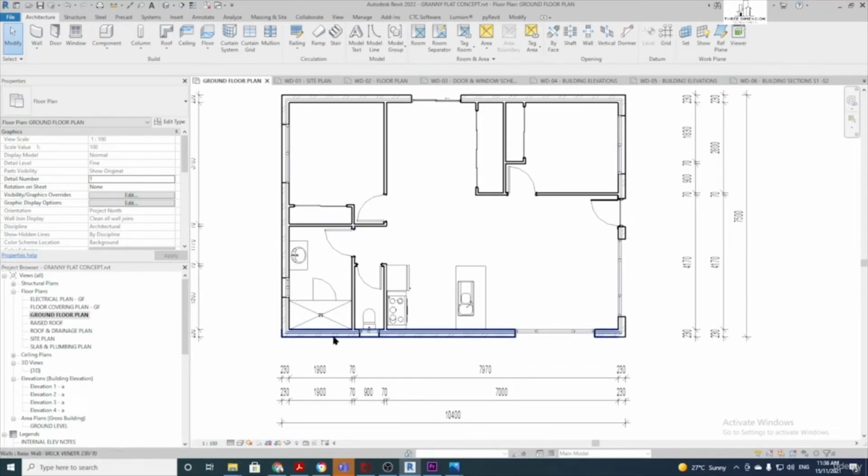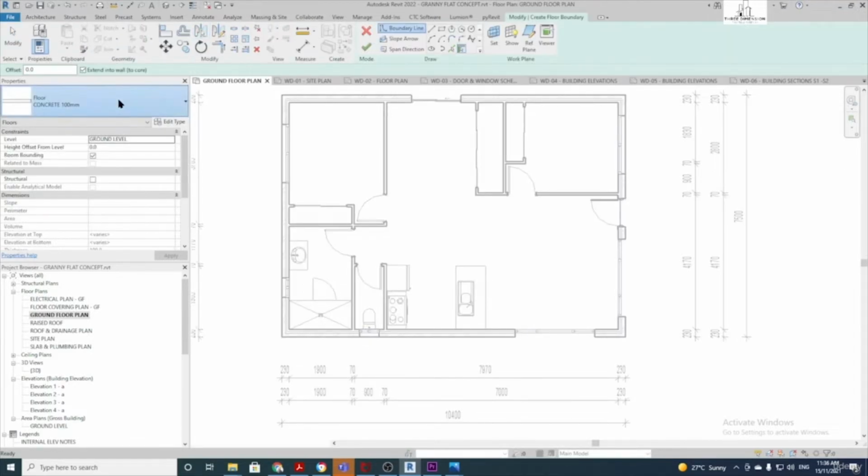And now we can put our wet area tiles in, so for our bathroom and our WC. So come back up to the floor tool, back up to our architecture floor, go down to wet area down the bottom here, use our pick walls tool again, come down here, we want to pick these external walls, pick these internal walls like this.